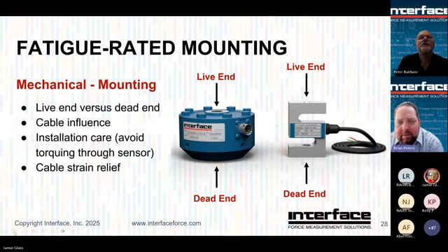Behind our label, that little blue label there, is where the gauges are. There's actually a little round cavity in there. We've got gauges on the top and bottom of it. So you can imagine that if that's where the force sensing is happening, if you were to strain relief the cable below it, it's not impacting the measurement. Now, if you were to pull that cable up and strain relief something on the top side of the string, well, now you have the cable influence impacting through a parasitic load path through the area of the bridge, in terms of what should only be seen, the axial load that's coming through the end of the load cell.